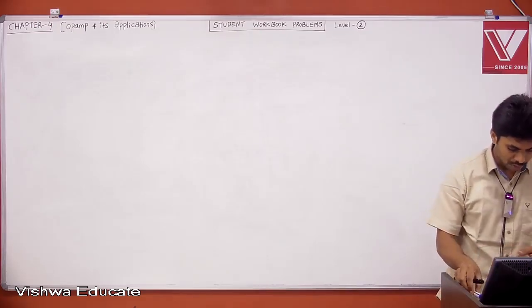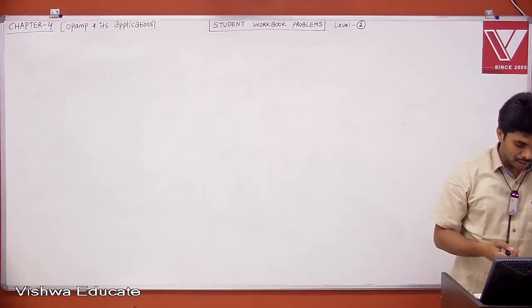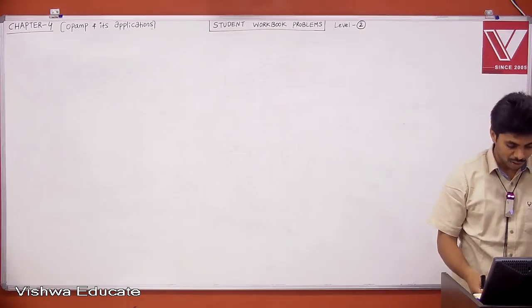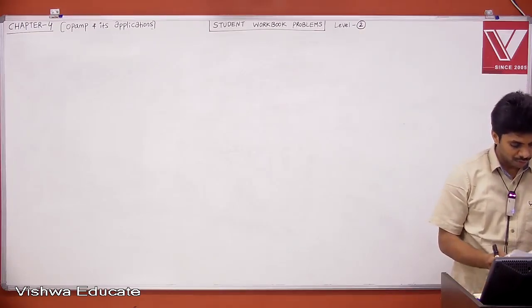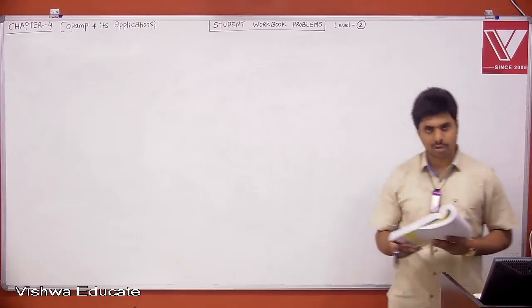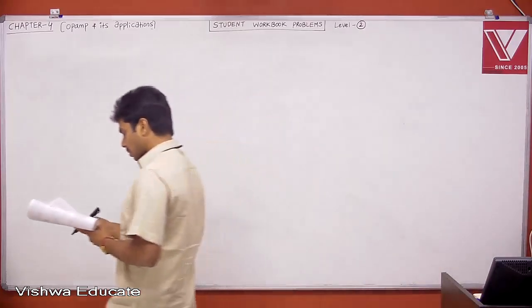Consider the following circuit using ideal op amp. The IV characteristics of the diode is described by the relation I is equal to I naught into e to the power of V by Vt minus 1, where Vt is equal to 25 millivolt, I naught is equal to 1 microampere, and V is voltage across the diode taken as positive for forward bias. That is what is our convention as well. The same thing is given.